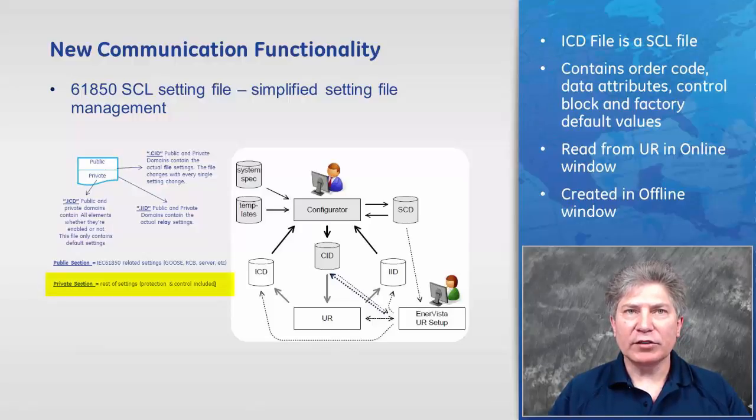The private section refers to everything other than IEC 61850, such as protection and control. It is not defined by the standard. Only the owner's tools are allowed to modify a private element. There are 3 file extensions: ICD, CID, and IID. We'll first look at the ICD.